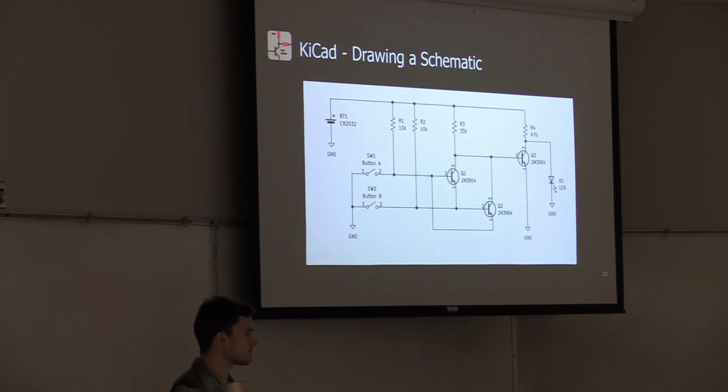So it's sort of like a give it power to the base, which is pin 2 in this case, and it'll allow current to flow from the collector to the emitter, or in this case, pin 3 to 1. And then to stop current flow, you remove power from the base, and it'll stop current going through it.